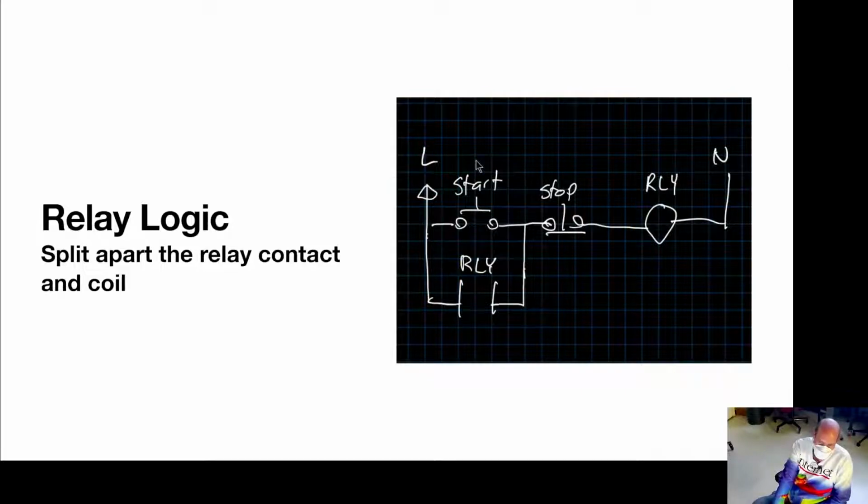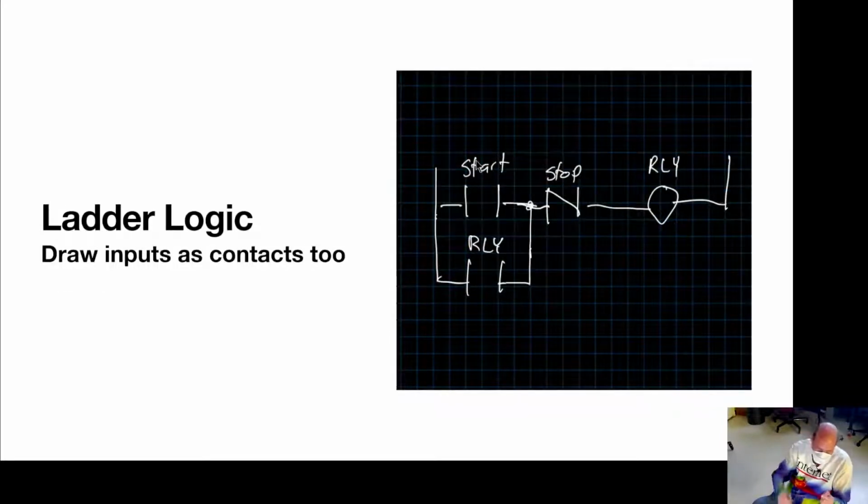But yeah, if you're looking at old pinball machines, their contacts are drawn this way, because, as you'll see later, you'll do electrical schematics using the logic symbols. So in this case, my start button turned into a normally open contact, and my stop button turned into a normally closed contact, is what the symbol is here. And my callout for which side is line and which side is neutral of the feed into this disappeared, because it's implied. As you'll see when things get more complicated, it just continues drawing longer.